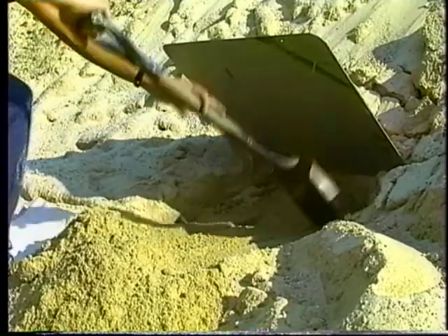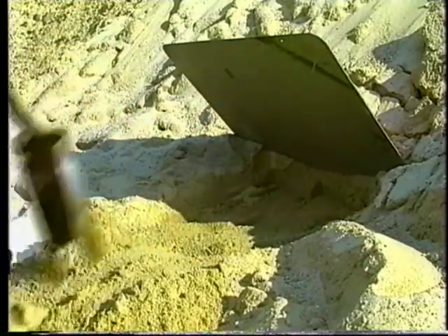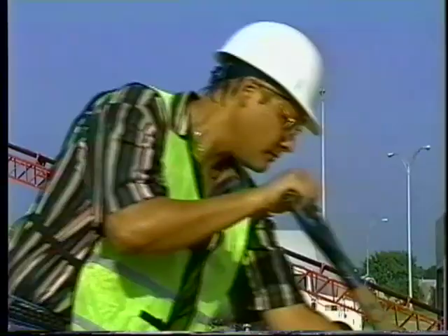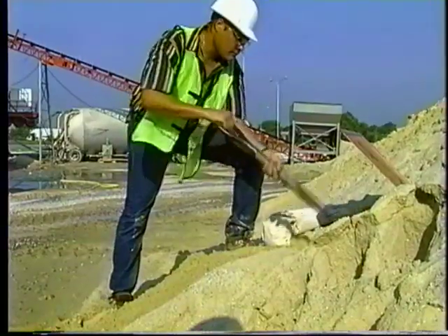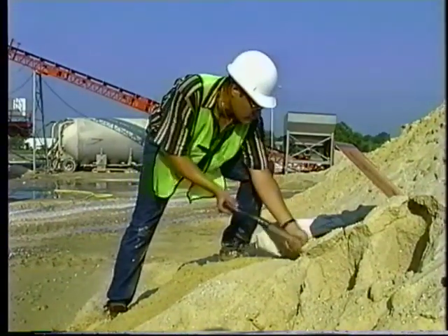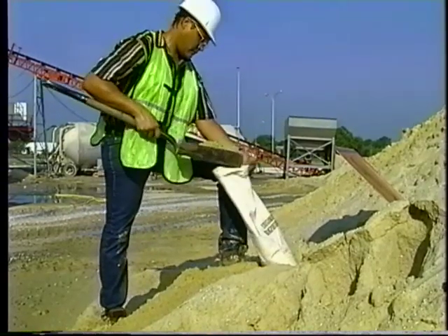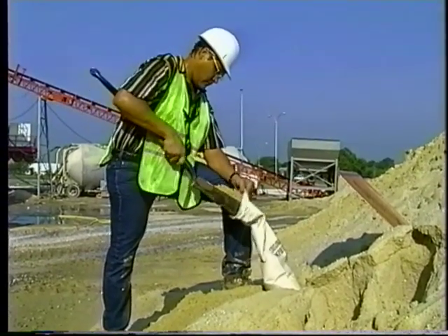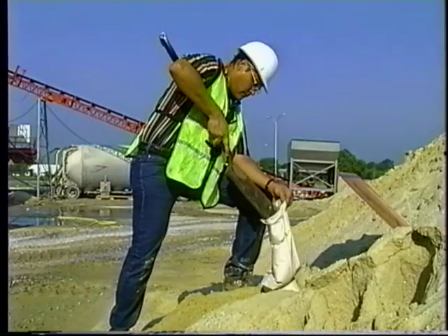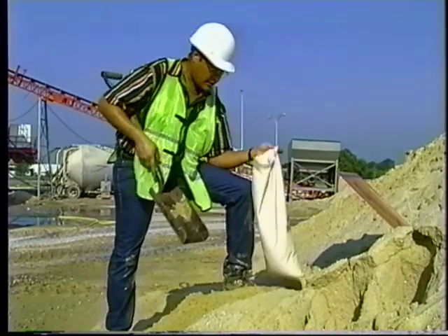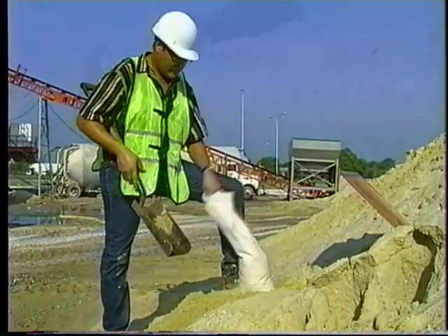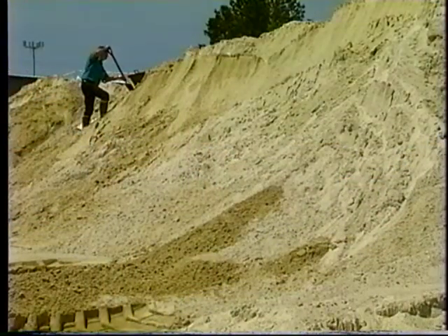Be sure to expose undisturbed representative material. Holding the sampling shovel perpendicular to the face of the stockpile, insert the shovel into the exposed material. Take the shovel full of material out of the stockpile and place it into the sampling sack. Be sure that you don't overfill the shovel. Repeat until 1/3 of the sample has been obtained. Move to the next location and repeat the process.